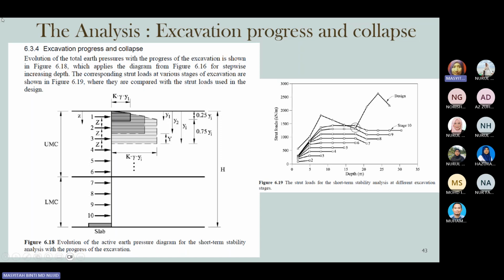So from here, you can see the evaluations of the total pressure with the progress of excavations, as shown in figure 6.18, which applies the diagram from figure 6.16. With the stepwise increase in depth, the corresponding strut loads at various stages of excavation are shown here. Meaning the strut loads apply, and then the depth increases, which gives a difference in forces, or different stresses, occurring behind the excavations. This can also be seen from the graph plot here.